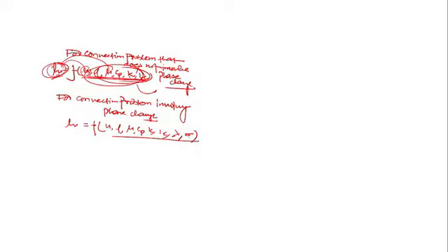And since the heat transfer coefficient depends upon various parameters, in order to simplify the analysis, there is a method called the dimensional analysis method. Through this method, I can reduce the number of variables by grouping them into dimensionless groups or dimensionless numbers. So that's why two numbers will come into the picture for the case that does not involve phase change.